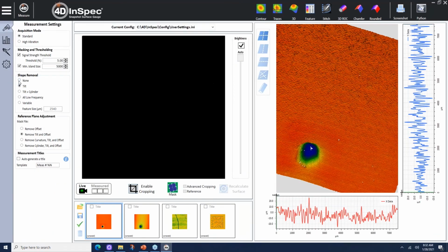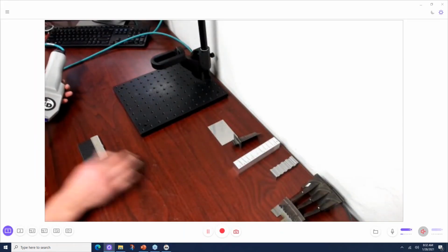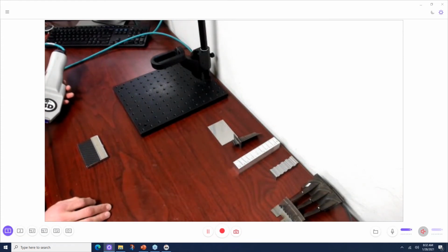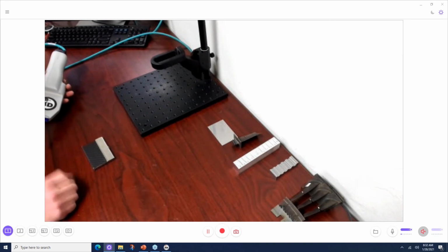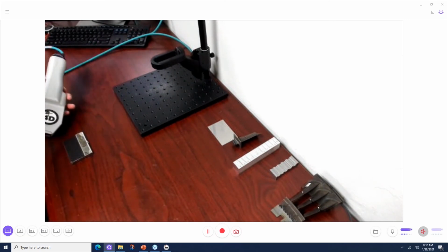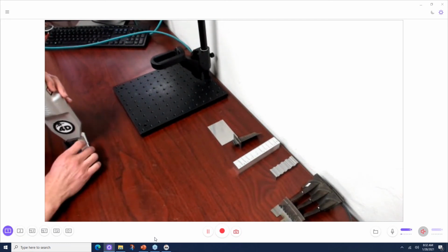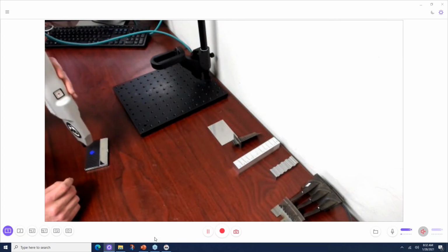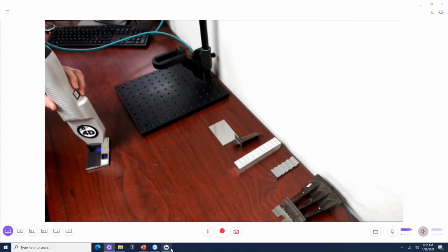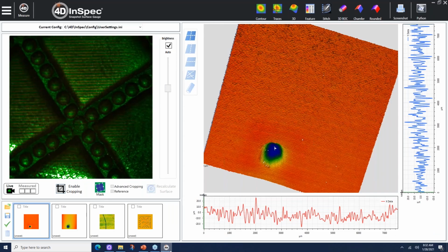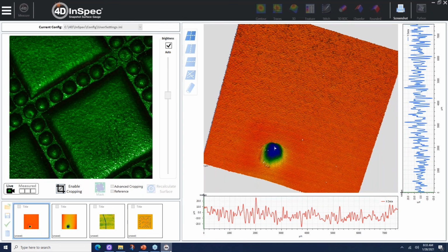And that's now black rubber, right, as your surface you're measuring? This is black rubber. So we can measure black rubber. We can measure the shiny material, the shiny metal. This is shiny too on it, but this is right here. But this black rubber is dark, and our auto brightness adjusts for that automatically, so you don't have to. But I'll take a measurement on this the same way I always do, placing this inspect down, the focus aid, and clicking that button. So I'll go ahead and go back to my live video. I'm in focus here, and I'll just take a measurement right there.